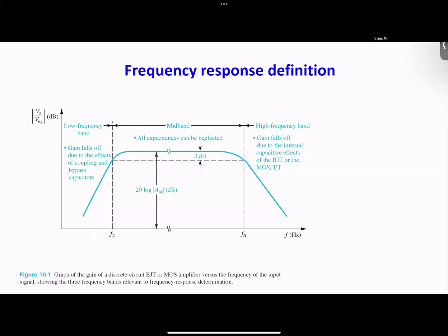It turned out in all amplifiers, this is actually what naturally happens. At low frequency, it doesn't work very well. At high frequency, it doesn't work very well. It only works in the middle band. If you want to increase your band, for a very low frequency application you have to select a very special transistor. If it doesn't work for very high frequency, you also have to select your transistor. Like if you go online, say to DigiKey, and buy parts to design your amplifier circuit, you have to specify your working frequency. You can't just buy anyone.